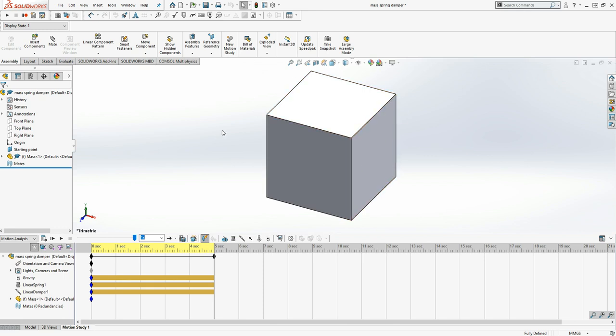This is one thing that's caught me out for years. It catches loads of us out. When SolidWorks first brings in a component, it assumes it's fixed to the ground. It likes to give you a reference point to start to build from. Because if it didn't, it would mean that when you go to build an assembly, every time you grab it, it might slip, and it can lead to a lot more frustrations. But because this is the only component that we're going to use, you see on the design tree, we've got the mass. Right click on the mass.